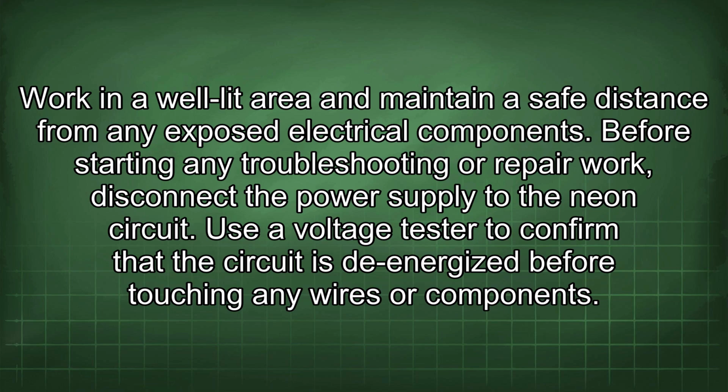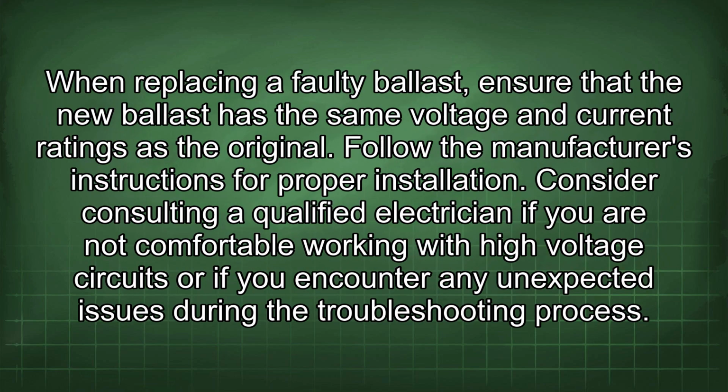Before starting any troubleshooting or repair work, disconnect the power supply to the neon circuit. Use a voltage tester to confirm that the circuit is energized before touching any wires or components. When replacing a faulty ballast, ensure that the new ballast has the same voltage and current ratings as the original. Follow the manufacturer's instructions for proper installation.